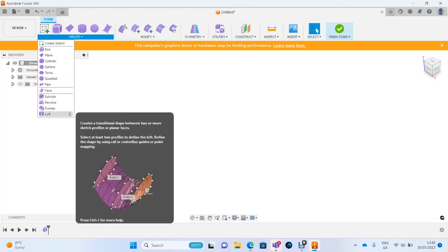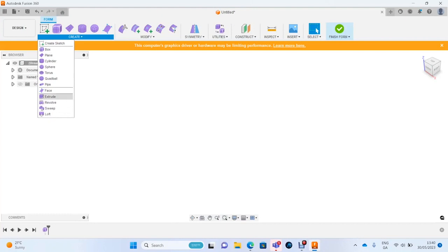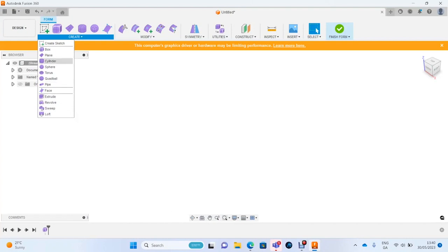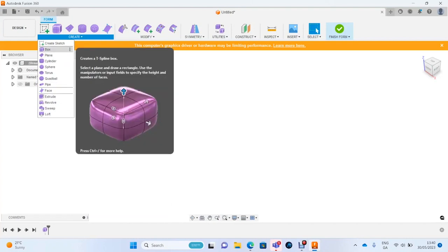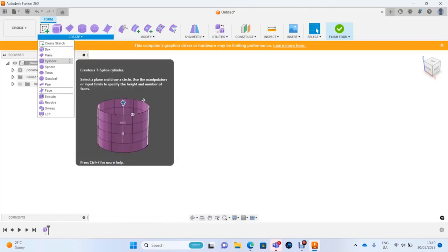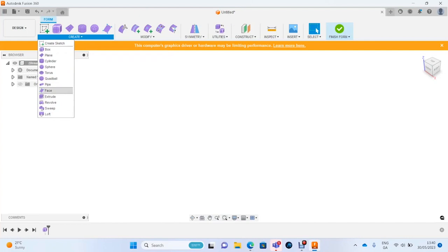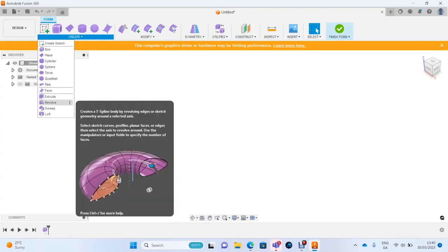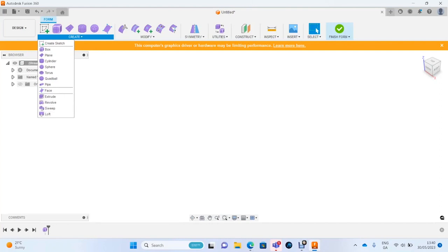environment, and they're useful, but for now we won't get into them too much, because generally it's easier to start off with one of these basic shapes and manipulate them into the shape you require, rather than extruding them. The reason I'm saying this is because when you generally extrude a shape, you end up creating more faces and edges, and that just makes the body difficult to work with.